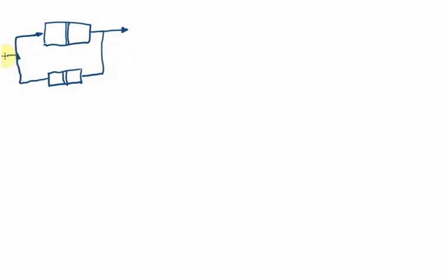Right, so once more, we have a stream that enters the primary PFR up here, and then at the exit from this PFR, we have a stream that exits the system and a side stream which splits down to a second PFR, and that exit rejoins the first stream. So there's basically a recycle through a PFR. So we want to determine the RTD in this situation. And the best way to do this is through a kind of thought experiment.